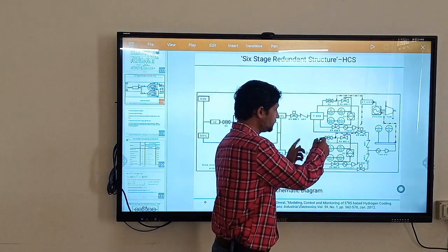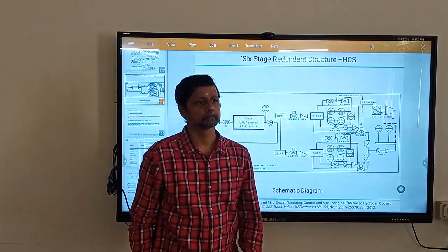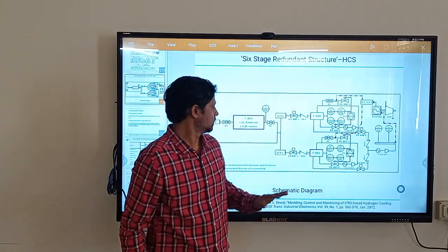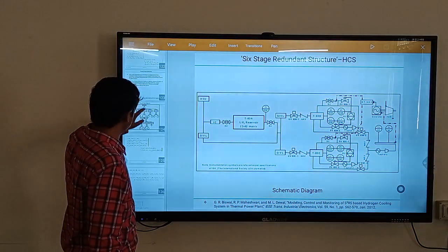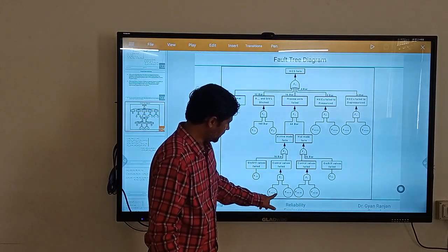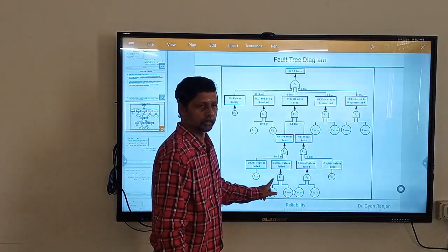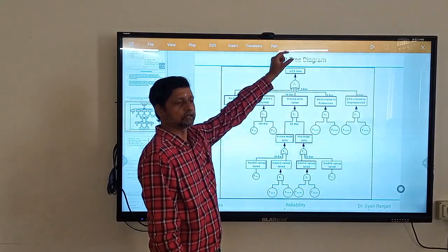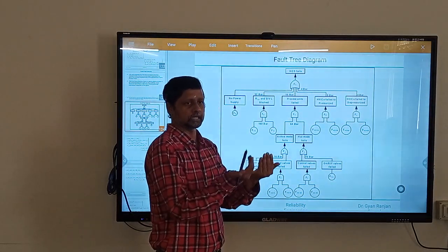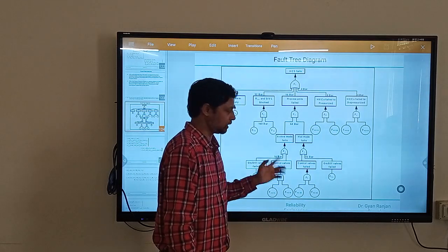Now imagine a scenario that all these critical failures are happening through both the lines at the same time. What will be the probability? Very less, but there is a probability. I can't say zero. Now let us see what the clear combination will be. Now, better for your understanding, you go from the bottom. I said that He1A and B were in parallel, right? Now both will fail. Both will fail. So parallel in reliability combination becomes series combination in failure. That means AND. We will form an AND logic. So Fy is basically the ANDing of He1A and He1B.